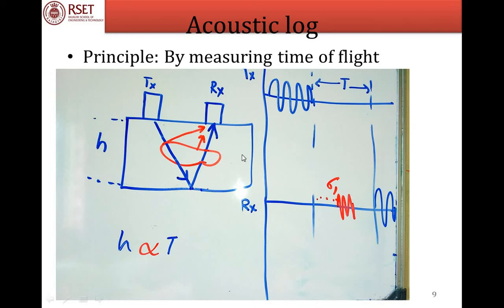Now, when there is no damage or holes present in this cast iron block, you can observe this waveform, both transmitted and received, in the cathode ray oscilloscope or digital storage oscilloscope after a time period T. Now suppose imagine that there is a hollow block, there is a hole present in the block.